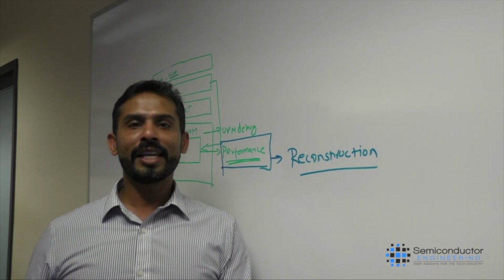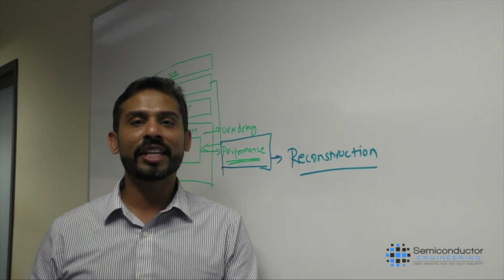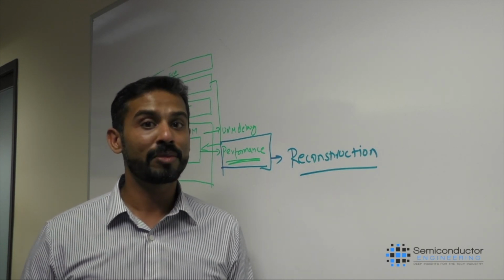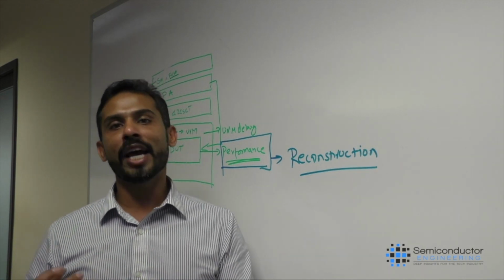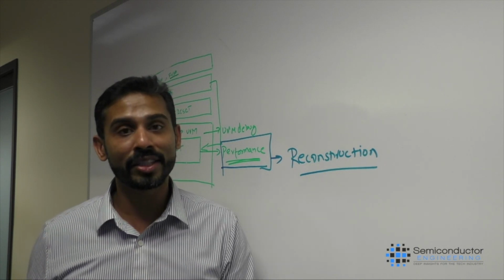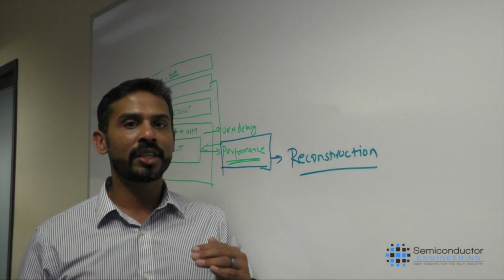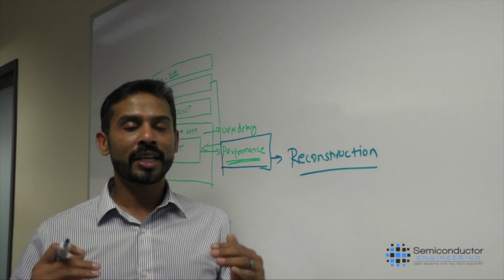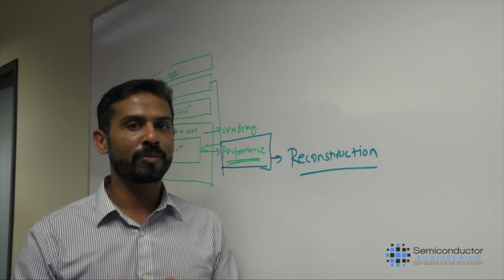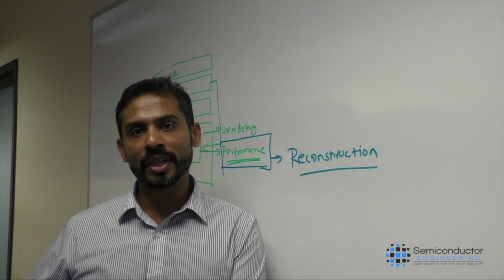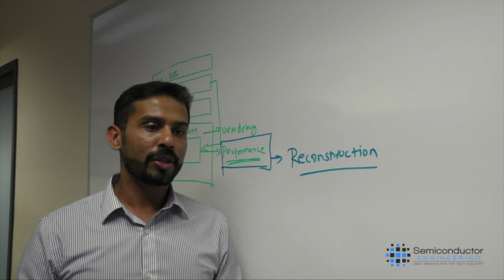So for an engine like a simulator, you can adjust the reconstruction to what the simulator engine needs. But for a prototyping system where FPGA data cannot be moved as much as you would like, you need much higher reconstruction. So based on what engine you are targeting, the ContextAware Debug platform from Mentor will adjust the reconstruction. It understands what the engine needs are, what the engine capacities are, and makes the data available for you.